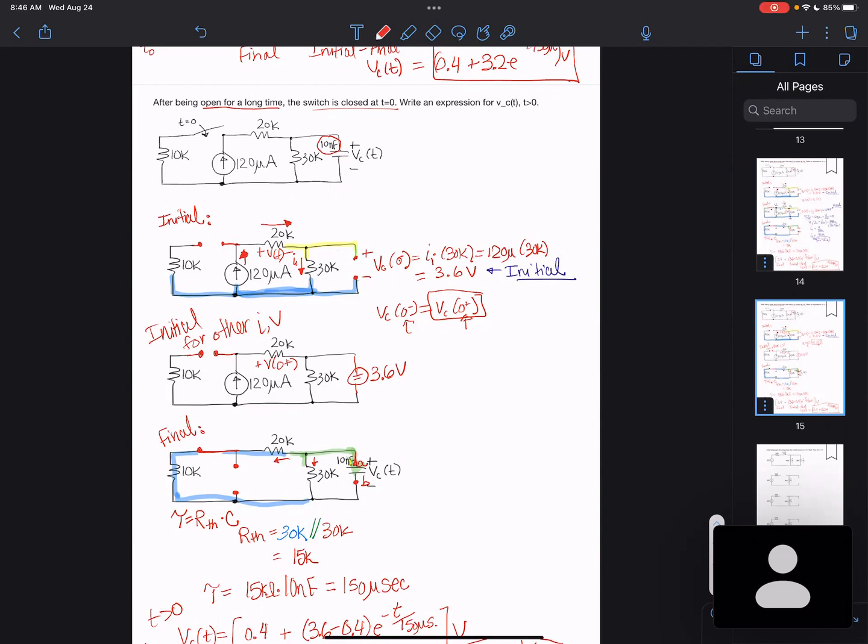A resistor can change instantaneously depending on what voltage I put on it, right? So like if I put a 5-volt battery, it's immediately going to have the current going through it of whatever the 5 over R. And if I put a 10-volt, immediately it's a new current value. So it can change instantaneously, but the capacitor cannot. So we have to use that characteristic to solve for any other voltage or current in the circuit.